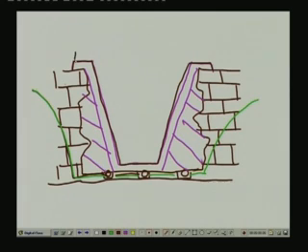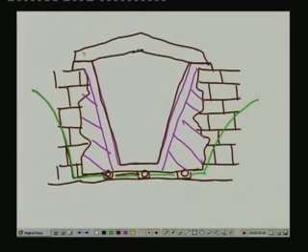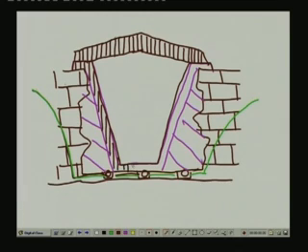and then waste was placed, and on top of the waste material was another cover comprised of very fine grained clay soil which is impervious for all practical purposes, and the top of the clay soil was sculpted to provide a surface slope so that any water due to rain or snowfall or whatever can flow away before it gets a chance of entering the waste placed within the landfill.